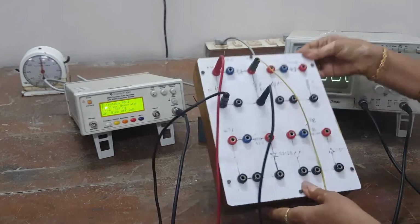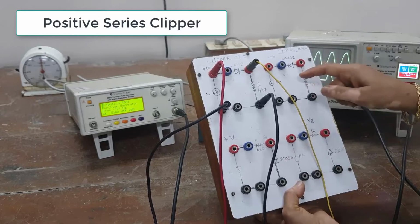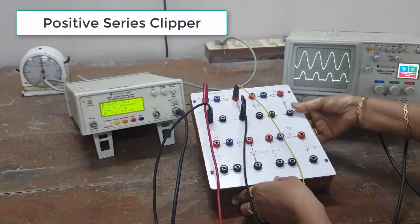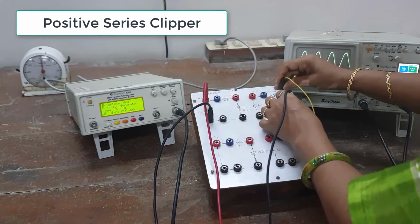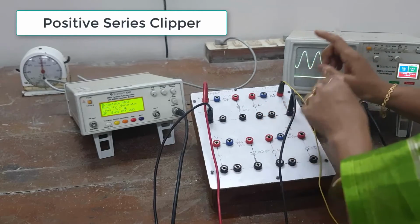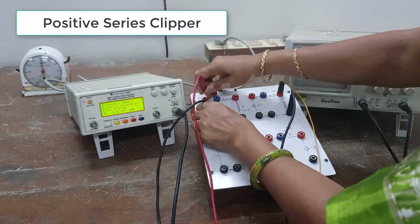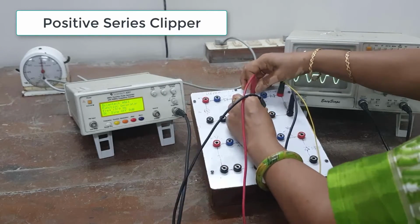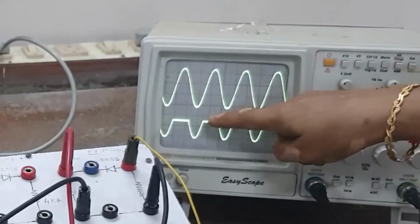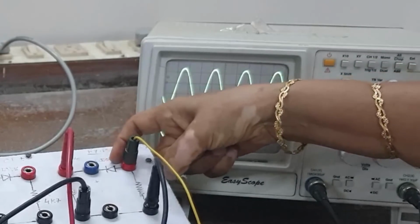The remaining experiments, like the positive clipper, we can also do the same way. Again you can take the output here. To get the positive clipper, we just have to change the polarity of the diode. The remaining everything will be the same. You give the input, take the output, and see the waveform. The positive half cycle has been clipped off. Here what we have done is the polarity of the diode has just been reversed.